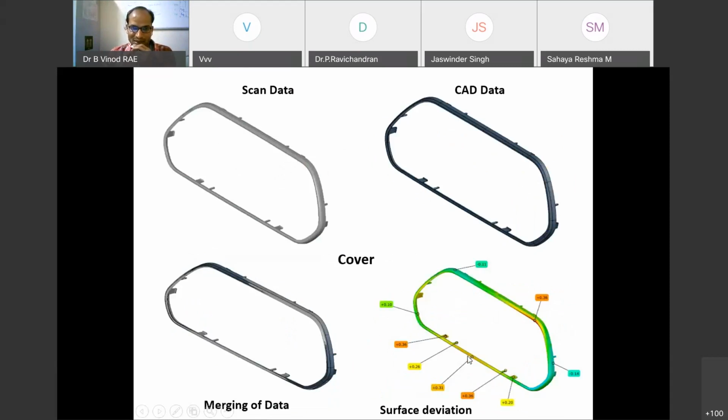Nowadays, the automobile industries are highly using this 3D scanner. They are merged with the robotic arm. Straight away, batch production comes. The robotic arm will scan the entire component in various positions. It automatically merges with the original CAD file. Then in another 10 to 15 minutes, we get the complete inspection report of the component in a series manner. So we can quickly identify where the problem happened, what the problem is, then quickly they will rectify it, then they will accept the component.